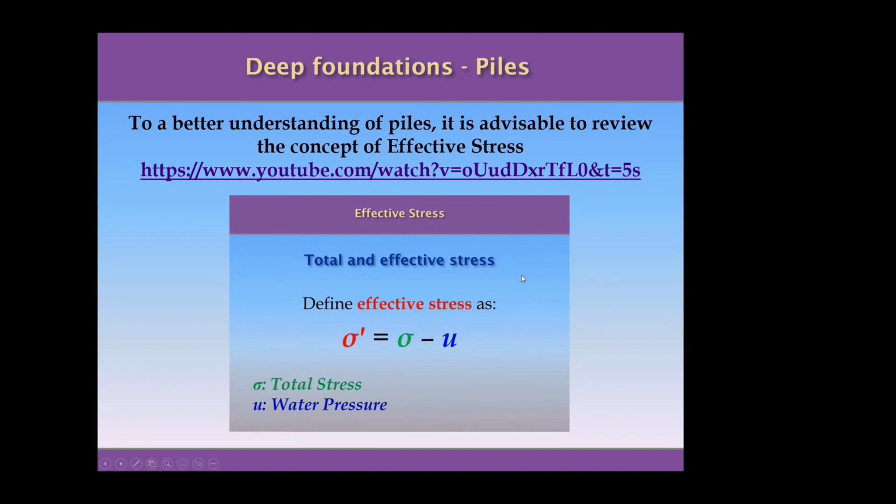So the important thing to remember is that the effective stress is equal to the total stress minus the pore water pressure. And to be able to sketch this pressure in a diagram that usually is a linear diagram because it's hydrostatic pressure, and to be able to determine the value of the effective stress at every level, and this is especially important in piles because a pile is a structure that goes deeper in the soil.